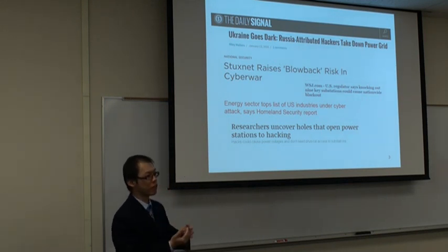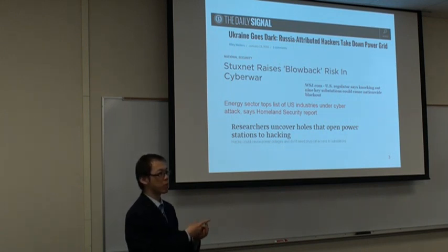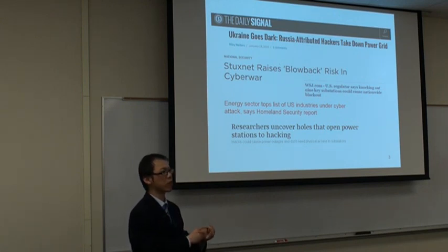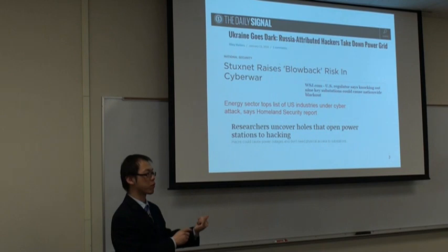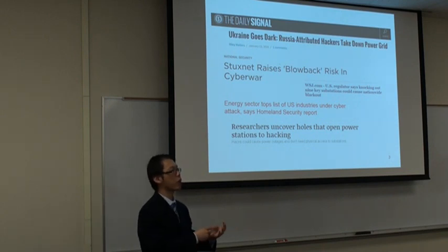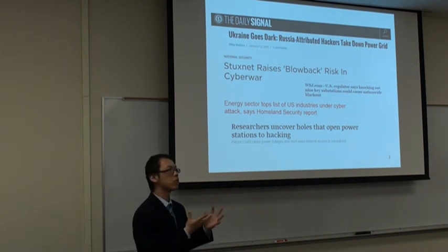So, for example, let's take a scalar measurement. There are real power, reactive power, current, voltage, and 3 phases for each voltage and current. We include the magnitude and phase angle, so that's probably 6 measurements for voltage, 6 measurements for current, and then the real power and reactive power also in 3 phases. This is just for one node, I think.